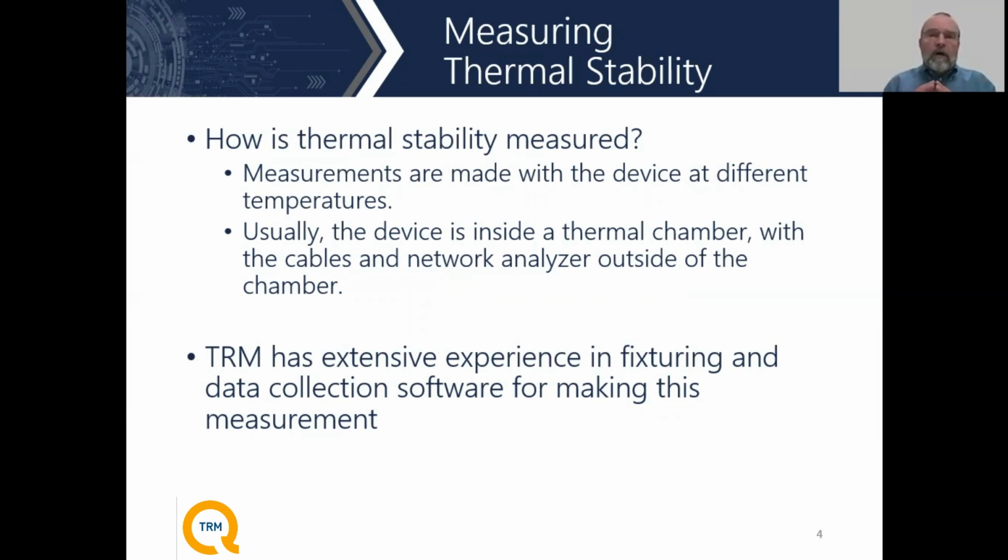So it is absolutely critical, and you can't be afraid to go through there and actually build custom fixturing that will allow you to dynamically change the temperature in the environment so that the unit that you're trying to test is at a specific temperature, and make sure that the temperature across the entire unit is uniform, and have all the measurement system, including the cables, outside of that environment where it's not affected by the thermal environment that you're making the test at.